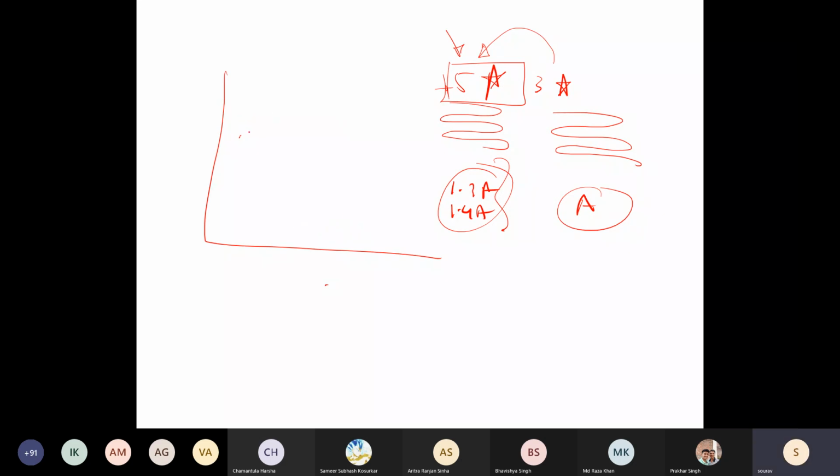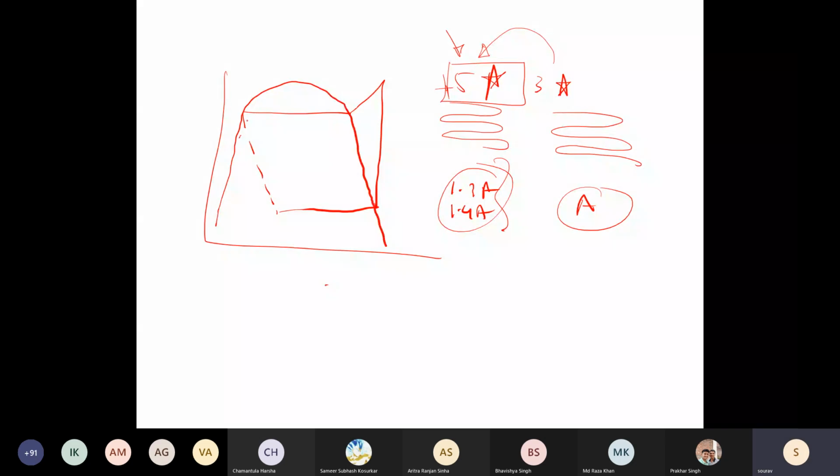Okay. So yeah, the last thing that we discussed in VCRS system was the actual cycle. So this is the standard cycle that we had been discussing. This is how your dome is. So you will have saturated liquid at the condensing end, saturated vapor at the exit of the evaporator. So sometimes this is also called as the single stage saturated cycle. Single stage saturated cycle. So single stage because it is only a single stage compression.